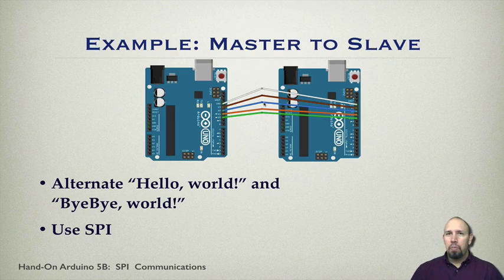Those grounds all need to be connected between these two. Each of the grounds, and the shield drain wire, also needs to be connected to a ground. So on one side, even though it looks like a single wire here, we actually have 5 wires connecting into that ground. And on this side we have 4 wires connected to the ground. That is, you only connect the drain wire up to one side. You don't connect it to both sides, otherwise you can create what's called a ground loop, and that's not a good plan.